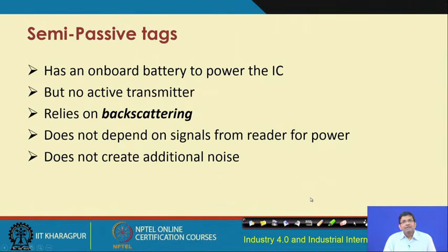So, there are semi-passive tags as well, which have an onboard battery to power the IC that is embedded inside these tags, and there is no active transmitter, but this mechanism also relies on the backscattering concept that I discussed previously for the passive RFID tags.